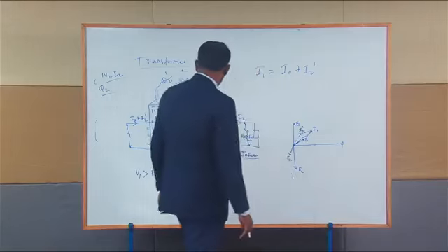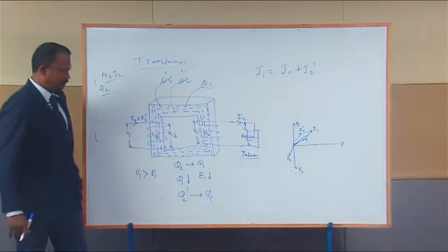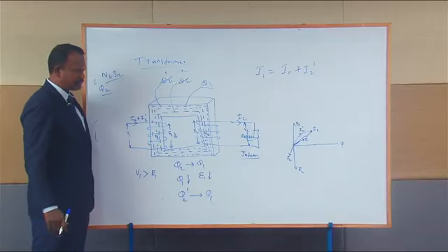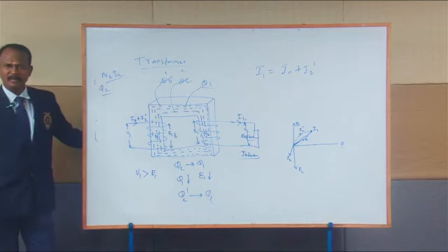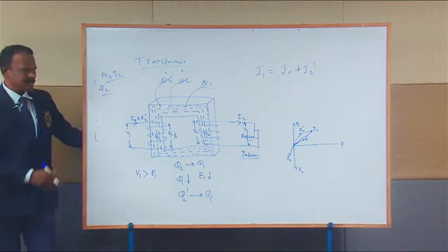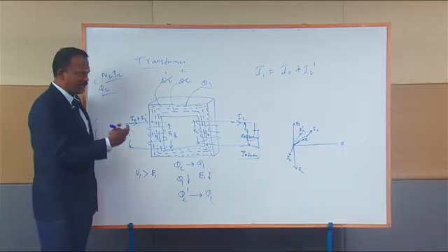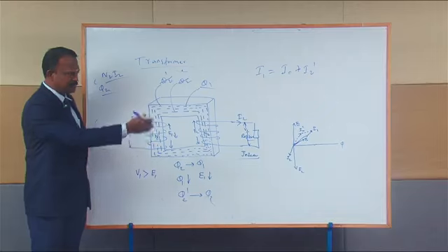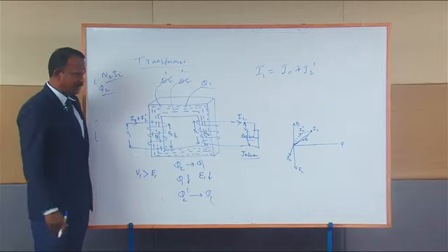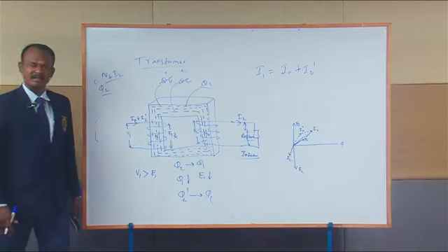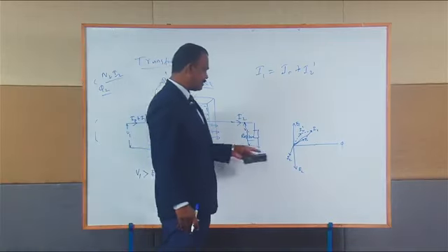Now when you look at this phasor diagram, we are not discussing the terminal voltage, because I said it is a lossless or ideal transformer. Normally your V1 voltage axis is also aligned with the same E1 direction, and V2 will be aligned with the current for resistive load.